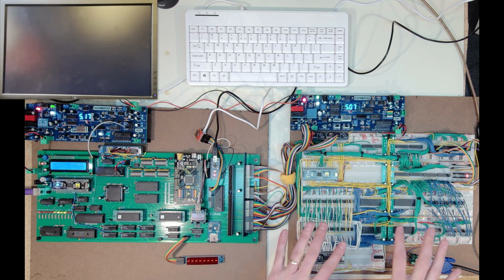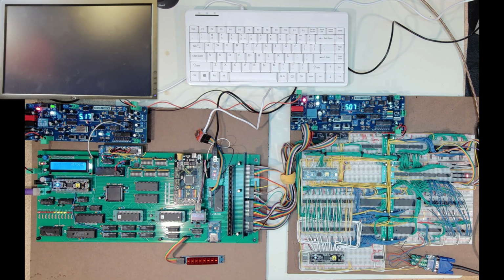And if you look at this mess that I have here, I think that's probably to be expected. I've got wires all over the place. They're crossing all over. I'm running a full 25 megahertz clock on this wire all the way over. I'm going through, I guess other things. I've got my pixel clock. I've got my VA0, so video address 0, which is a fast moving signal also. I'm running that over, plus I'm running an inverted version over, so all that really high speed stuff I think is pretty much staying down here for the most part. I do also run some of that up here.